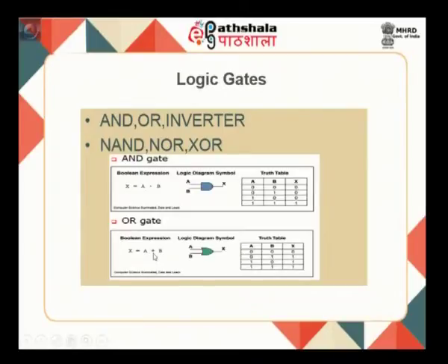Now I will go ahead with my OR gate, a plus b. The symbol itself tells you that it is like addition. This is the symbol with which the OR gate is represented. It takes 2 inputs and 1 output. With 2 inputs, as I said, I can make 4 different combinations: 0 0, 0 1, 1 0 and 1 1.